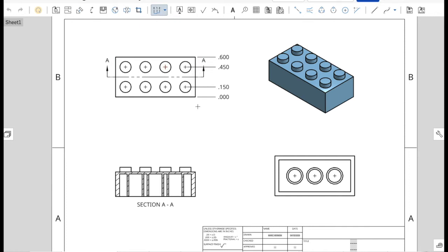I'll click Ordinate Dimension again, and we'll do it on this side. I'll come out here and bring a 0 out there. I like to have the 0, if I'm going to dimension down both sides and up, put your 0 point at the exact same point. So count up and count over, or something like that. Then I'm going to click in all of these. This might be a little over dimensioning. Some people might not like it, but I think it's okay.